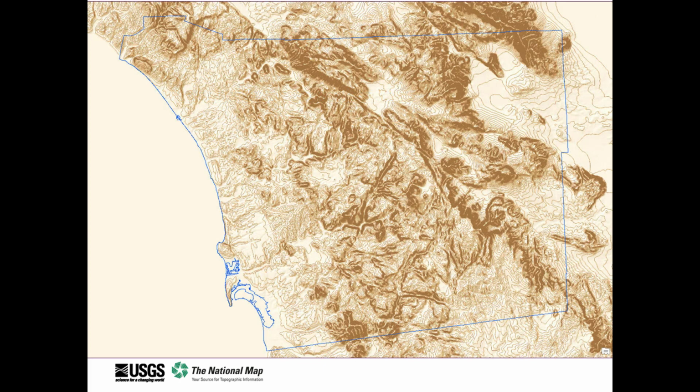This image, for example, shows the USGS shaded relief and contour line map services turned on within ArcMap software over San Diego County. No data files were downloaded to view the data. The map services are simply turned on. Since the data are being viewed in a geographic information system, you could also bring in additional local data, which can be displayed along with the 3DEP products. Lesson 5 in this instructional series provides further instructions on how to use the National Map web services in ArcMap.